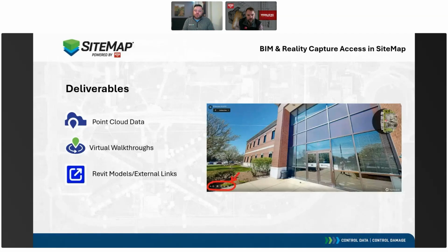We have a number of different tools we use for reality capture. If we start off with the virtual tour from a Matterport camera, or from other systems that we have, they claim 3/4 inch accuracy, but over the global it may be a little bit more than that. It may not be quite 3/4 inch from one end of the building to the other. It may be 6 inches or a foot off over the length of a building, but still pretty accurate and still pretty valuable for most of our clients.